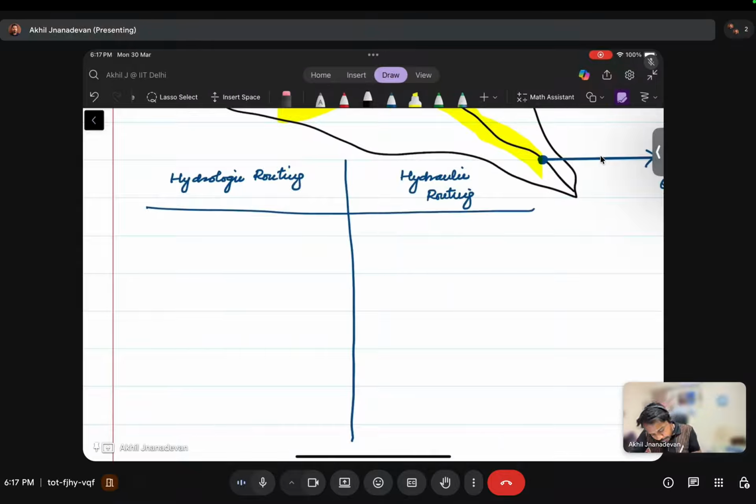So in the case of hydraulic routing, when we are trying to model, we use the RTT and apply the system of equations that are defined in the Lagrangian frame of reference to the Eulerian frame, where the fluids can be defined, right? So here also we will be routing with the help of our standard conservation laws.